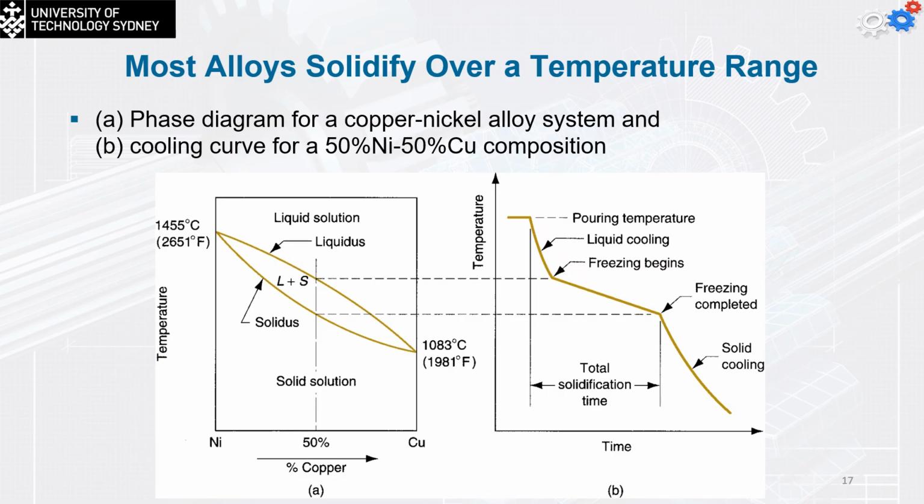We add the temperature, we add the heat. So again, to reach the melting temperature of the first metal, it starts to melt, while the other one will remain as a solid. So again, we have mixtures of solid and liquid in the middle, until we reach the temperature for melting the second metal, and thus both are going to be liquid. We add more heat, we're going to reach the pouring temperature. So we're going to pour the metal inside the mold.